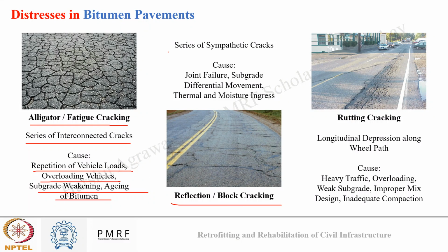They appear as a series of sympathetic cracks, as shown in the image. And they are caused basically due to joint failure, subgrade differential movement, and thermal and moisture ingress. Then we have rutting cracking.